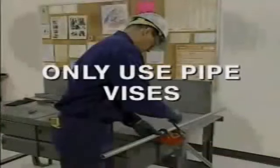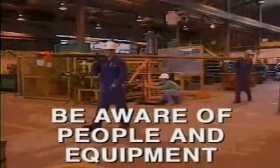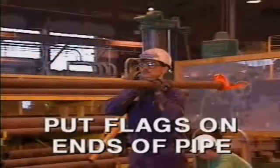Only use vices equipped with special jaws for holding and protecting pipes. Conventional vice jaws can damage pipes. Be aware of the people and equipment around you when you're handling or transporting pipes. Put flags on the ends of long lengths of pipe so that you and others can easily see the ends and avoid damage or injury.